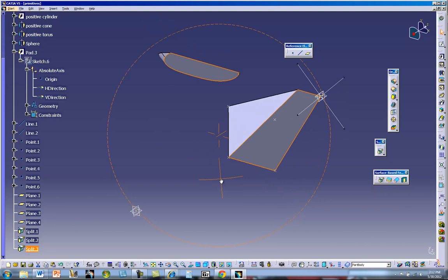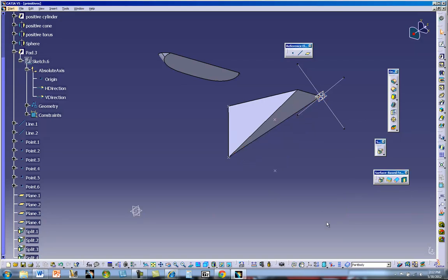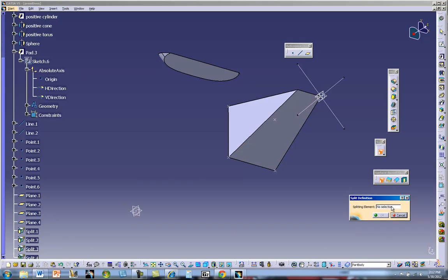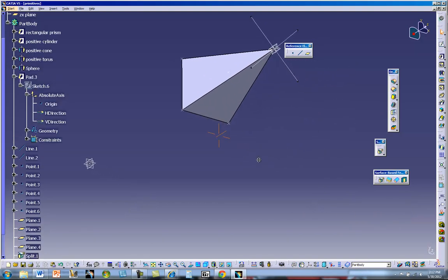And now we want to go, and one more time, plane 4. Where did plane 4 go? There it is. Let's try reversing it, because you want whatever's cut off. That did it just the opposite. I was wrong. Control Z. Plane 4 again. Turn the splitter on here. Double highlight that. Plane 4. Hit OK. And then you've got yourself a